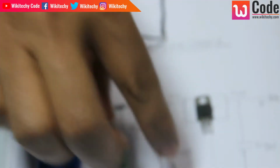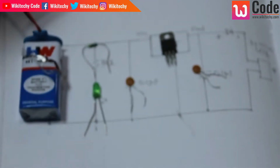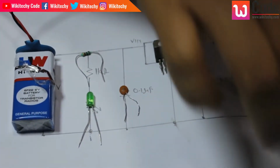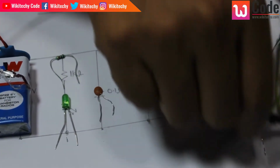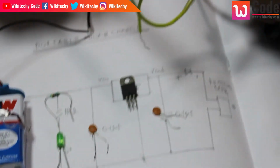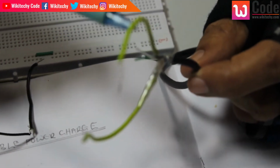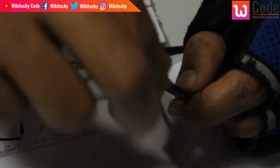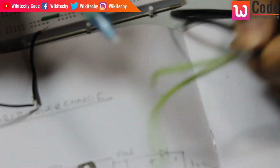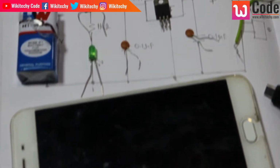I place this capacitor here and another capacitor here, and this is my battery USB charger. In this USB charger we got 4 wires. One is a red wire, and the other is a black wire for ground, and we got a green wire and a white wire. Just leave those, we don't want them. And you connect your mobile here, and your charger is ready.